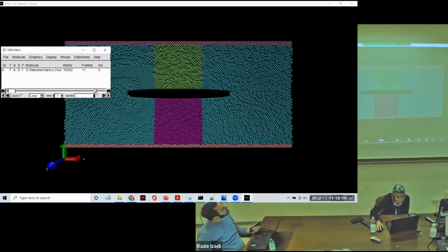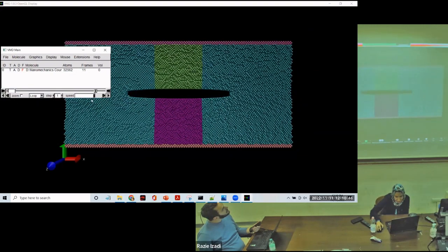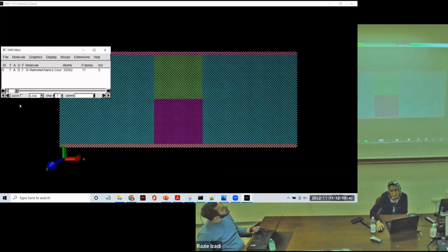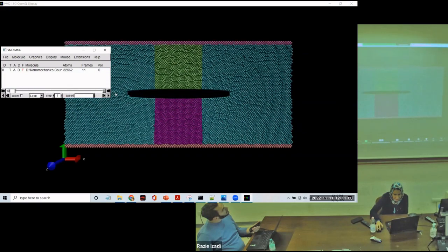This is what the metallic part looks like. You see that the type of failure is a bit different from the other one. That was something like a fracture, so you could see the cracks there, but here it's ductile, and you mostly see the slippage of the crystals on each other instead of breaking and fracture.